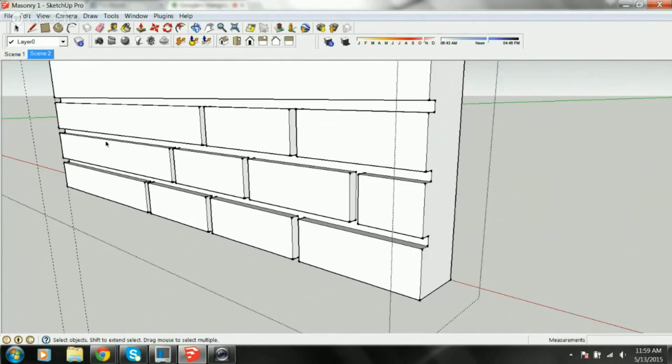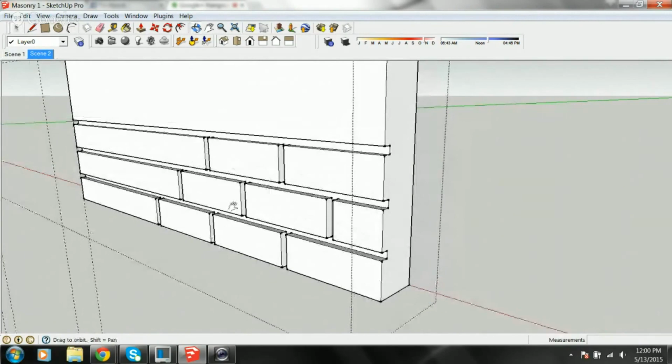To apply the mesh that I've got, which is basically a plug-in to SketchUp, I select the faces, and it basically turns all the faces into a 3D mesh that has surface texture, and I can vary the surface texture as much as I want. But I'm going to run into limitations with Shapeways because of their polygon count and their file size. I think we're at a 60 meg file size. Something like 2 million polygons. I don't remember what it is. I think it's 1.3 or 1.6, but whatever.